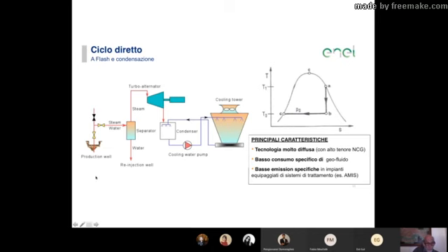So out of the production well comes out vapor, which usually is at the top at about 20 bars. 20 bars vapor that goes through the vapor duct to the separator at the entrance in the geothermal power plant. And this vapor goes through the turbo alternator, and condenses right at the end here.